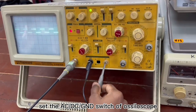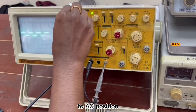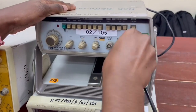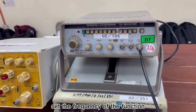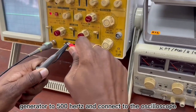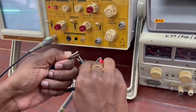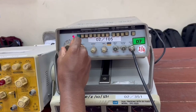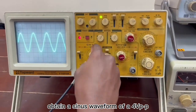Set the AC or DC or GND switch of the oscilloscope to the AC position. Set the frequency of the function generator to 500 Hz and connect it to the oscilloscope. Obtain a sinus waveform of 4 VPP.